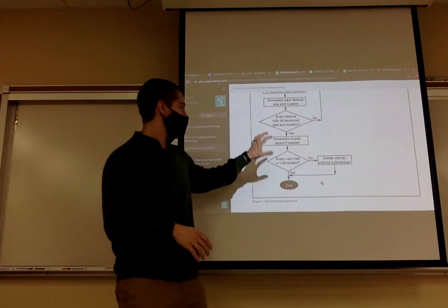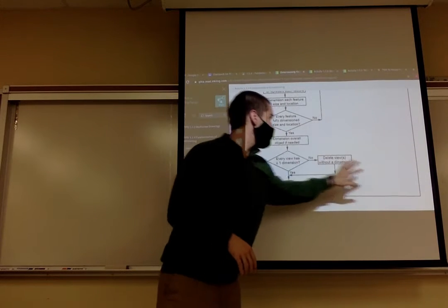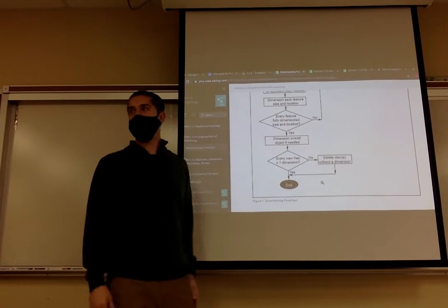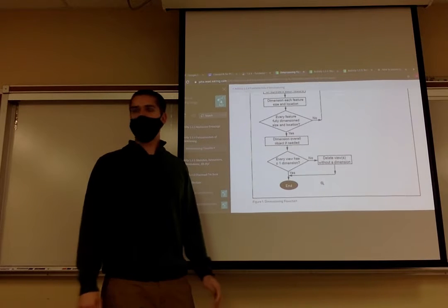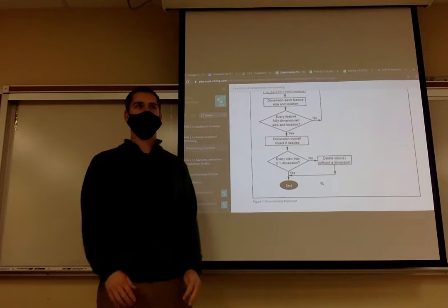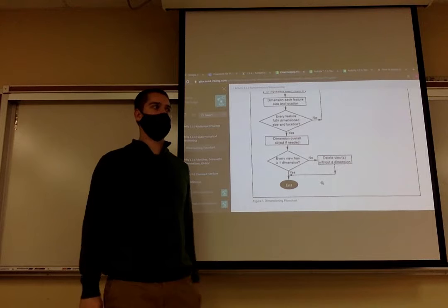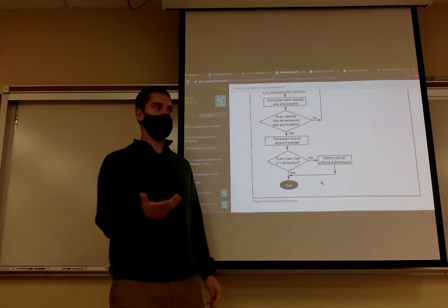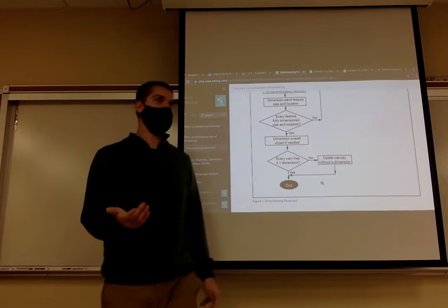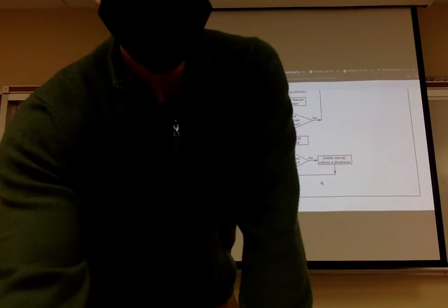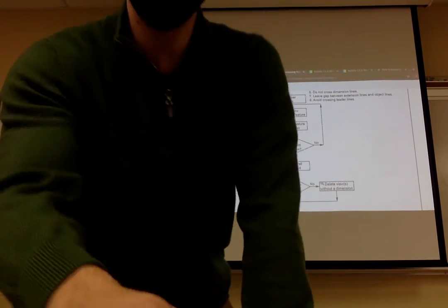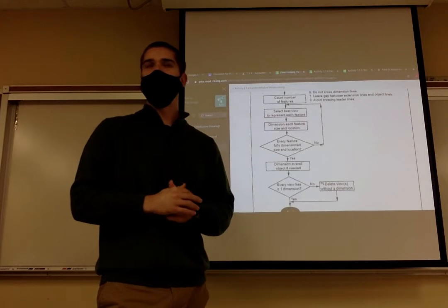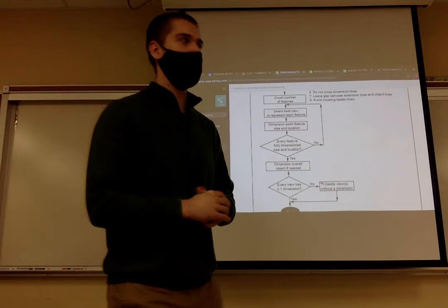So you always start with your front, right, and top views with the ISO. And after you finish dimensioning, if there's a view that doesn't have any dimension, delete it, because whoever you're giving this to doesn't get anything out of seeing a view with no information about it besides what it looks like. So again, this resource is on 1.2.4, so you could always review back, like, oh crap, how do I go through dimensioning again?